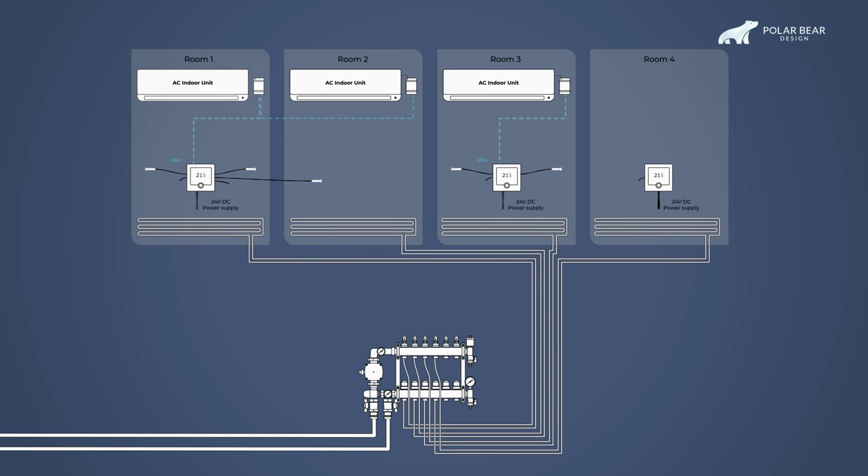An important side note for systems with underfloor heating is regarding the need to measure the temperature of the floor itself. Obviously, limiting the floor temperature will prevent damage by overheating, but we can also enforce a minimum temperature to help keep the system responsive. To be able to do this, the thermostat needs to be able to measure the temperature of the floor, so adding in floor sensors is a must.